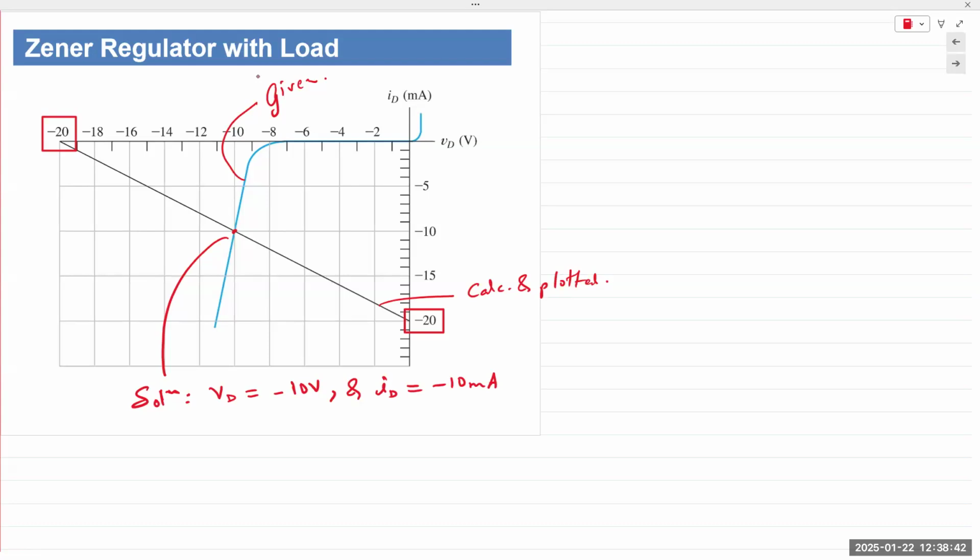Yes. It actually doesn't matter. You can go clockwise, you can go counterclockwise. Answers would always be the same. Typically, most students from their physics classes or prior classes are used to taking a voltage and then dividing up the voltage across all the components, so they get supply voltage is equal to something. And I'm always used to just writing all of the voltages out, equating it to 0, and then putting a plus sign, minus sign, however I go. That's what I always state. If you have a preferred method, stick with it.